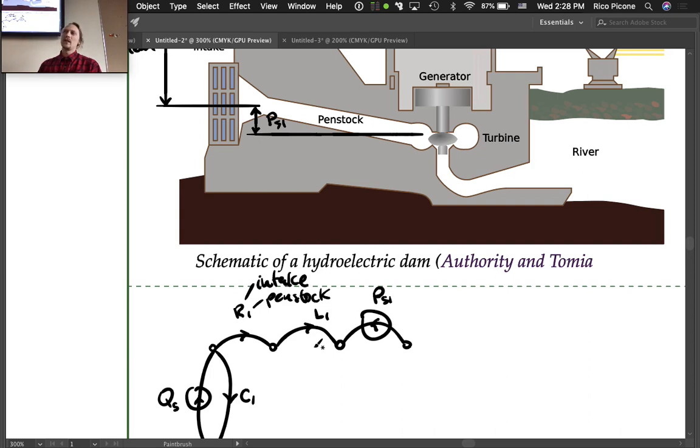There are other ways you could interpret that as well. Well, logically, it just seems like they should be in parallel considering it's one component doing all three of these things. Right. Yeah. So what does happen though is that these intermediate nodes are nonsensical nodes. We wouldn't think of what is the pressure here. It doesn't really make a lot of sense. The pressure drop across R1 and the pressure drop across L1 taken separately isn't really something that is relevant. So we can mix these around in any order, and the intermediate nodes are not really of interest.